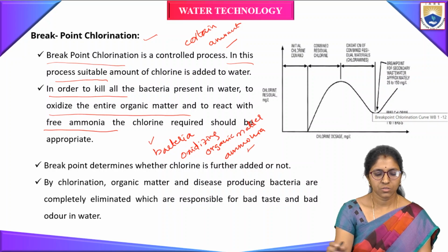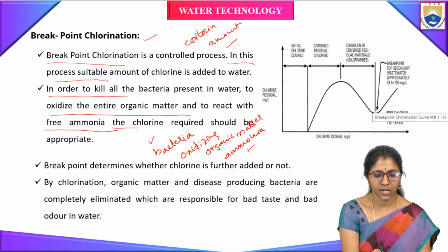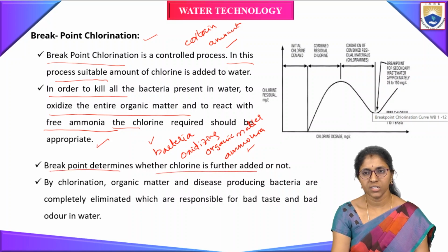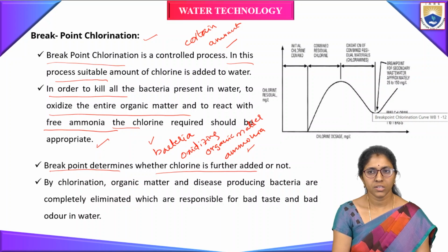So this breakpoint chlorination is used to kill all the bacteria present in water, to oxidize the entire organic matter and also to react with the free ammonia. This process is very useful. Here the breakpoint determines whether chlorine is further added or not.